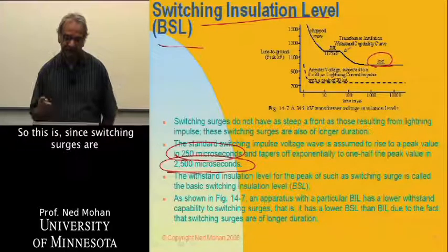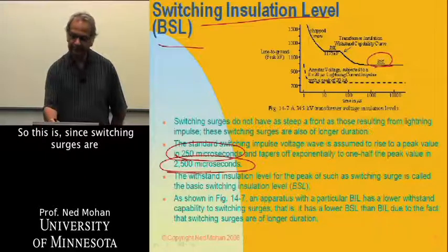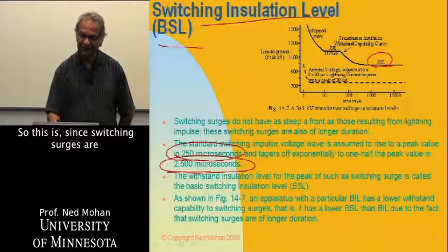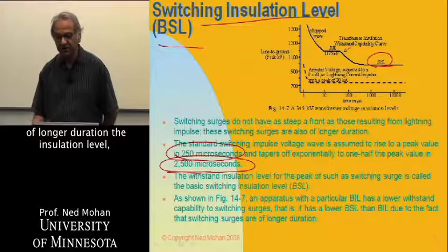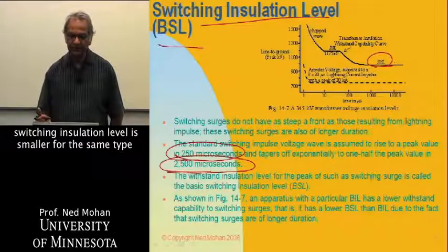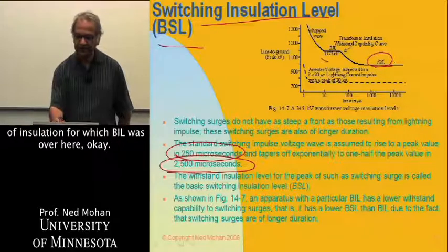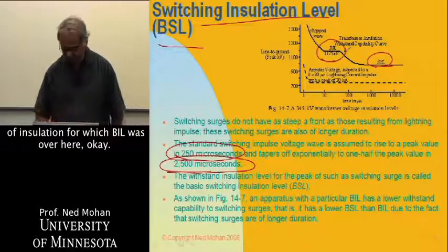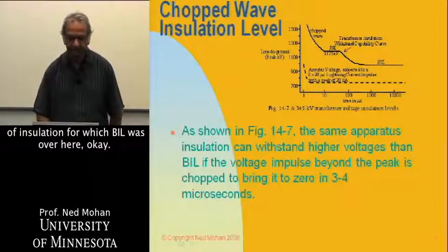Since switching surges are of longer duration, the switching insulation level is smaller for the same type of insulation for which this BIL was given.